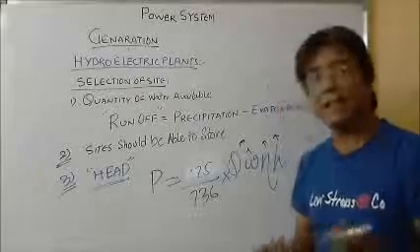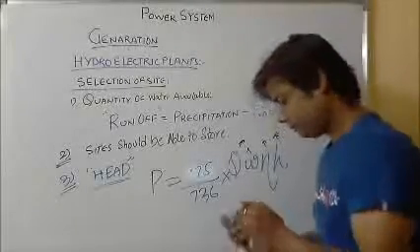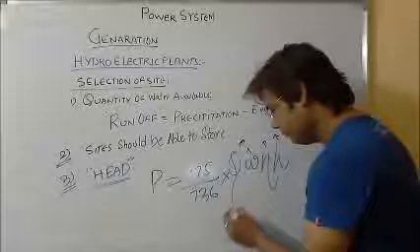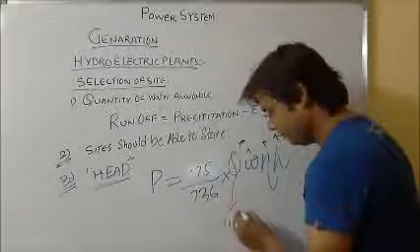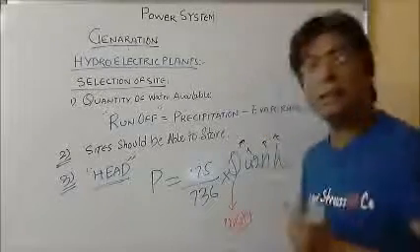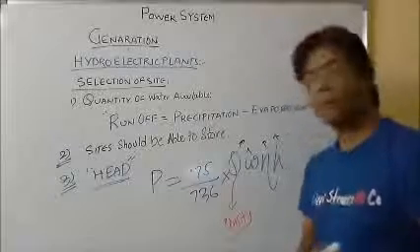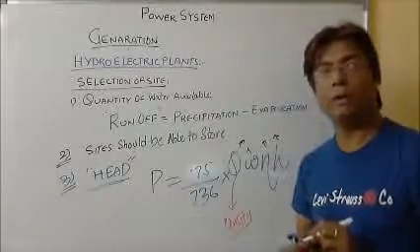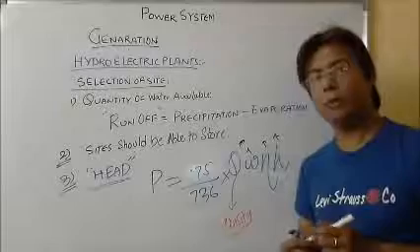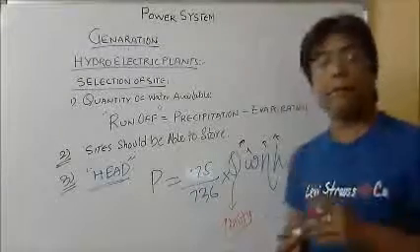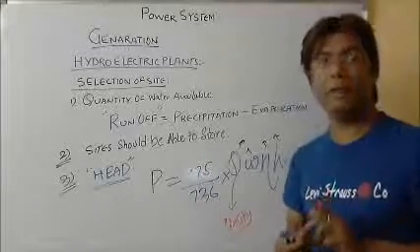Q is the discharge, in meter cube per second. How much water is flowing, that is called the discharge. W is the density of the water. This density is fixed for a type of water, for a place, or even if it fluctuates, there will not be much difference.